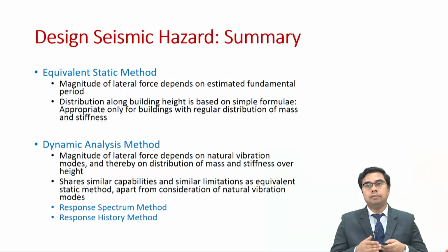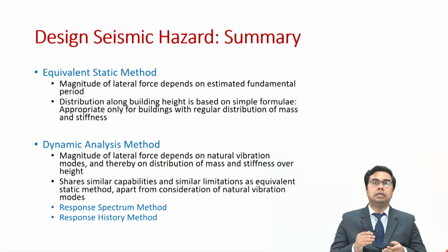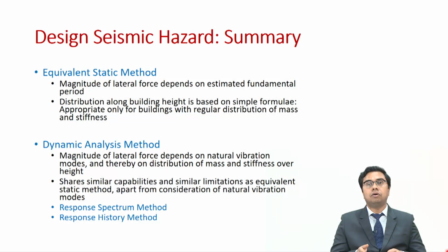Further on, we looked into dynamic analysis method, particularly two methods, which are response spectrum method and response history method. And as it is clear, these methods are based on few, if not all, modes of oscillations of the building, and therefore the magnitude of lateral force depends on different natural vibration modes, and thereby the distribution of mass and stiffness over height has been considered. However, other limitations of equivalent static methods is still present in the dynamic analysis method.